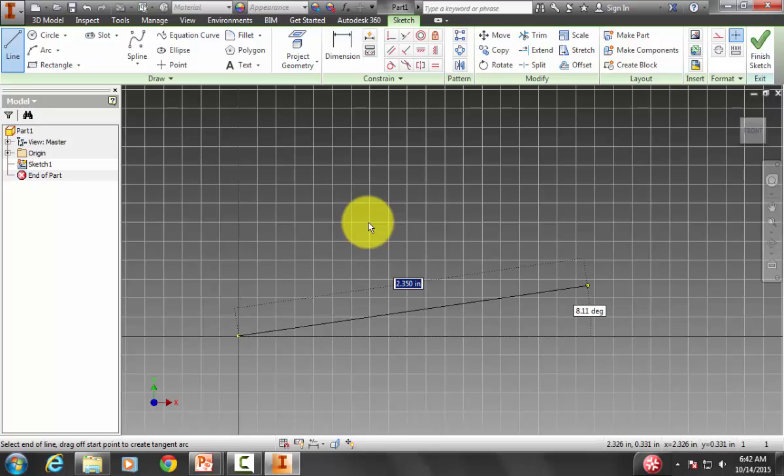I pull out. Now I'm going to have this 3 blocks long, or 3 blocks wide in the front. So 0.75 is the dimension of each block. So that's going to be 3 times 0.75 or 2.25, but I can also type 3 times 0.75, and as soon as it turns black, I'm okay. So it did the arithmetic for me.